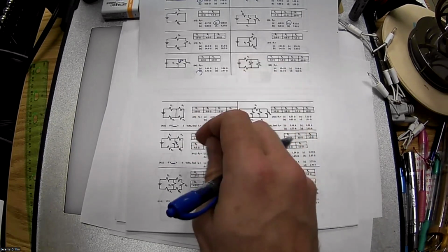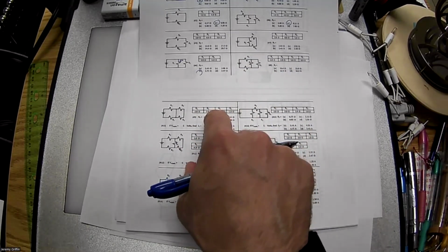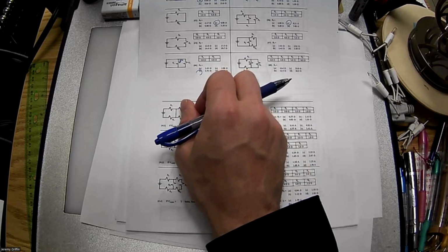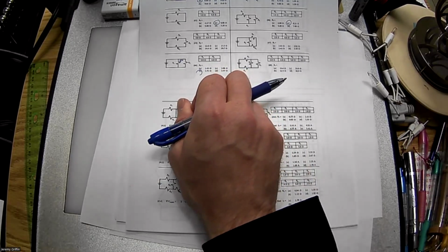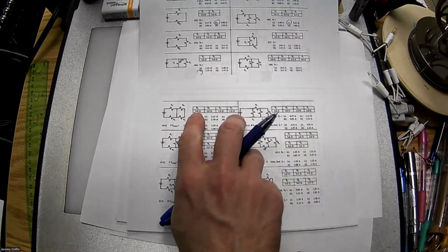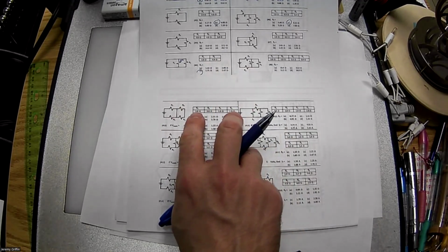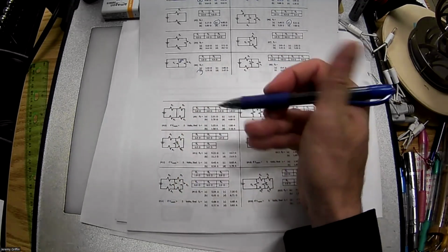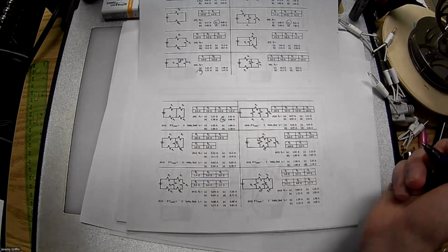R2 and R3 are not even part of the circuit. I could have made up any numbers there. I could have made 1 ohm and a billion ohms. It wouldn't even matter. You just ignore them. There's your circuit. You guys see that's your entire circuit? Doesn't that look exactly like number 2 that we just did a few minutes ago? So R1 and R4, those are the only resistors part of the circuit. Are those in series or parallel? Series. Can you just very simply add R1 and R4? So for me, 3 ohms and 1 ohm makes 4 ohms. Boom, done.